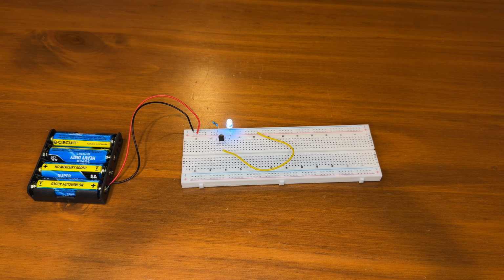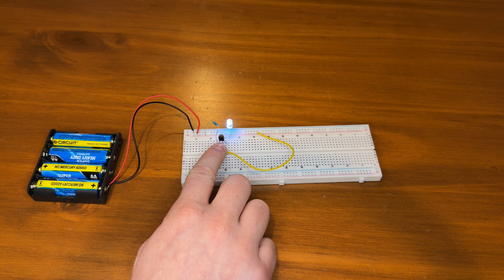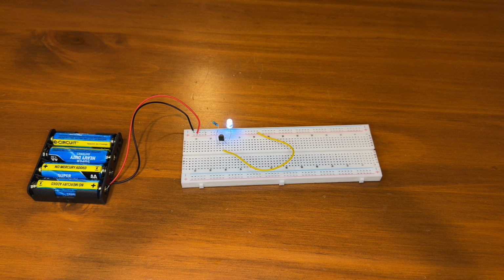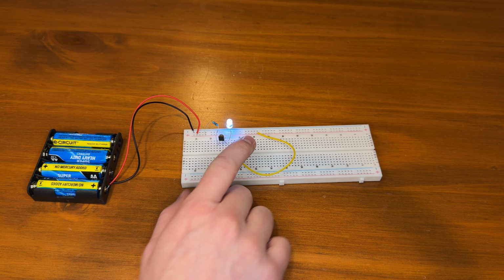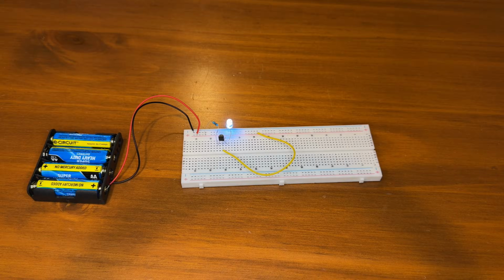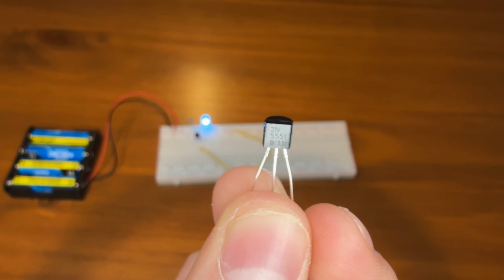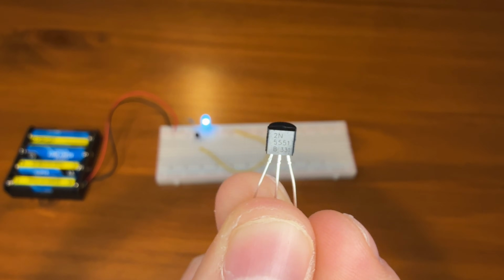One important thing to remember is that transistors must be connected in the correct orientation. Different transistor models may have their pins arranged differently, so it's important to identify the collector, base, and emitter before placing a transistor into a circuit. The transistors included in this kit are labeled with part numbers that can be used to find their specifications.